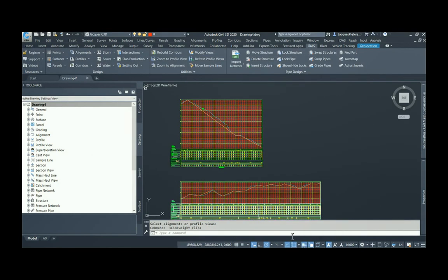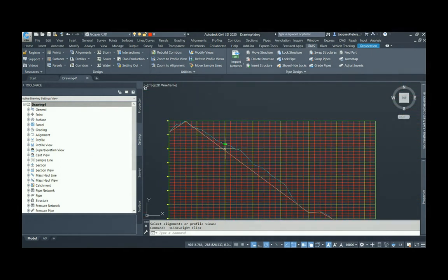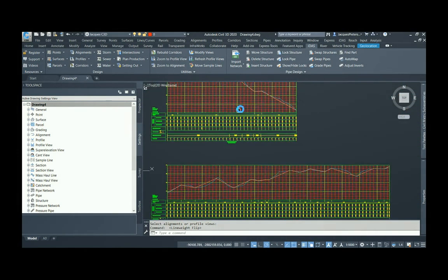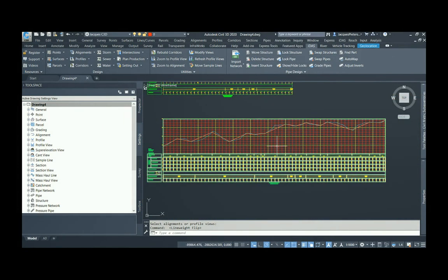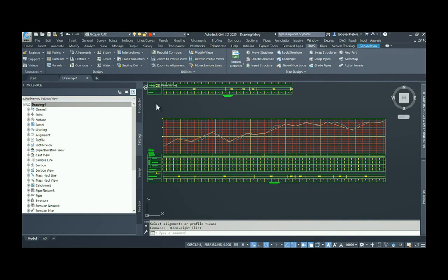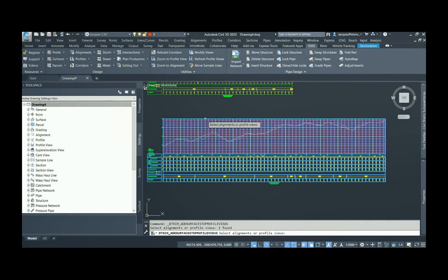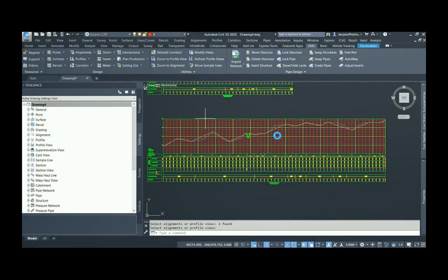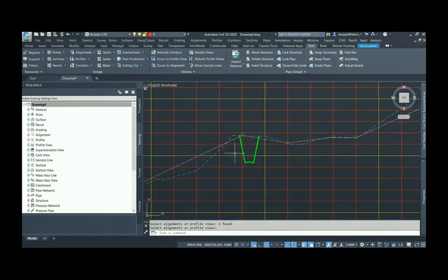If I switch on my line weight, you can see the representation of that road in this profile view. So you can do this for multiple views. Now this is for Vessel Road. If I want to see the display of 10th Avenue top of surface, I can go back to the profiles again and specify, this time, 10th Avenue top. Select the profile view, press enter, say okay and yes, and Bob's your uncle. There you go.